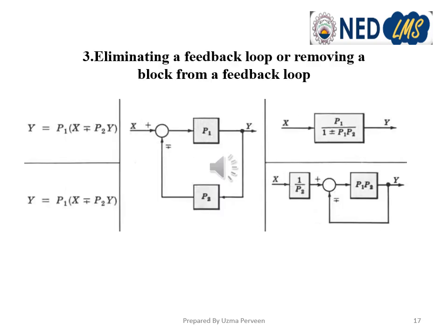This is a very important transformation in which we actually eliminate a feedback loop. The transfer function is g upon 1 plus gh. You already know we have derived c upon r equals to g upon 1 plus gh. So in this case, p1 is g and p2 is h. So the transfer function will be g upon 1 plus minus gh. Again, the sign in the denominator is actually the reverse from the block diagram.